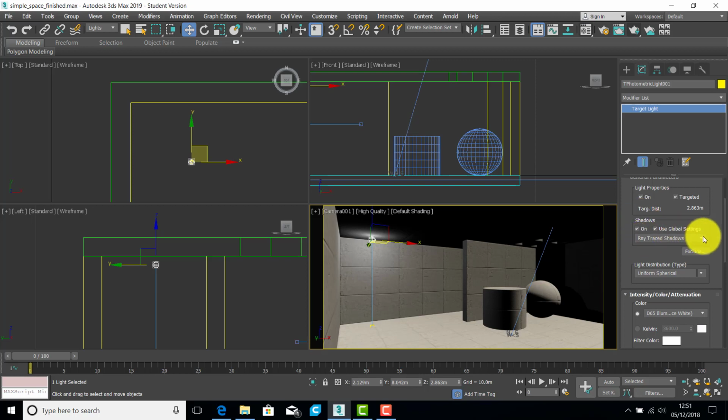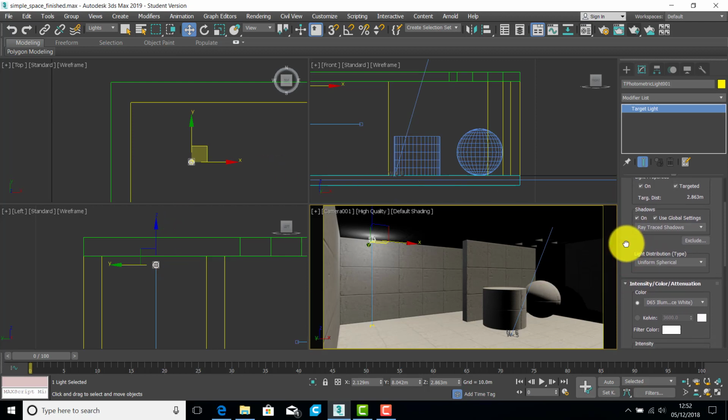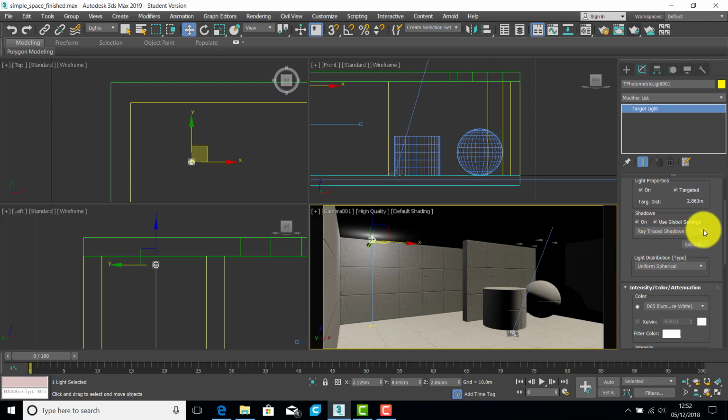What type of shadows though? Now this can be a bit annoying in the way that the software shows you options that aren't necessarily available to the objects you're looking at. So these area shadows aren't pickable for the light source that I'm using. They're automated actually for these photometric lights, but there's sometimes you encounter settings in 3D Studio that it displays, but they aren't relevant to your particular object, and that can confuse people.